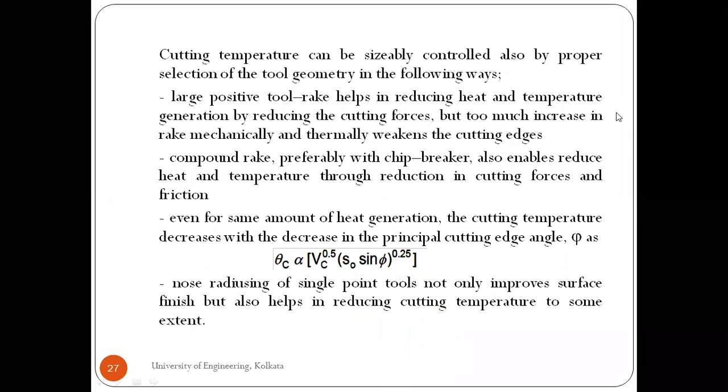So definitely, again, a very small rake angle is not desirable, right? So we have to select the optimum rake. So that is what it says, that too much increase in the rake mechanically and thermally weakens the cutting edges. Again, compound rake, preferably with the chip breaker.